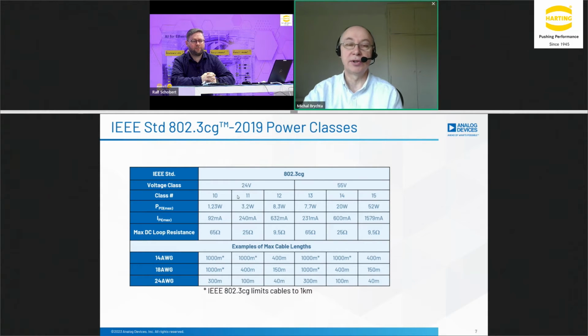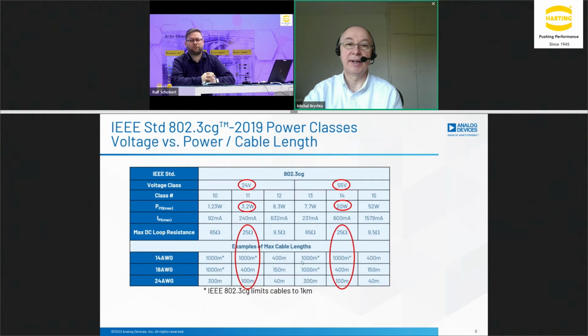For various reasons. One reason is, especially in factory, 24 volt is a very common low voltage power supply for pretty much everything, for PLC, for actuators, and so on. Also, in some environment, like wet environment, 24 volt is the safe voltage. So you can't go much above 24 volts for a safe operation in wet environments. But then there is advantage of using high voltages as well, and I'll show you this on the next slide.